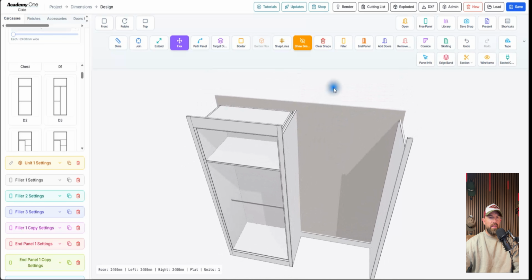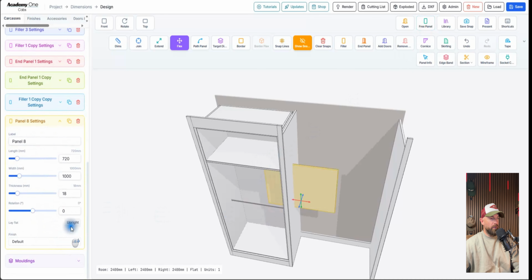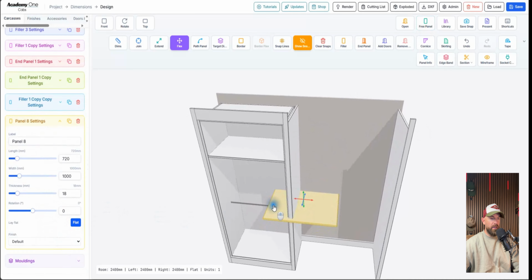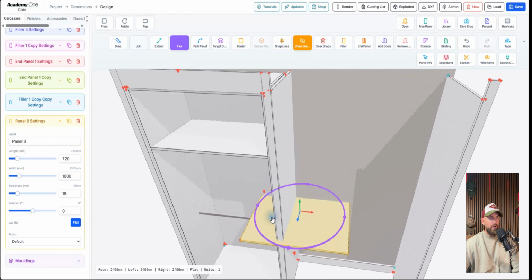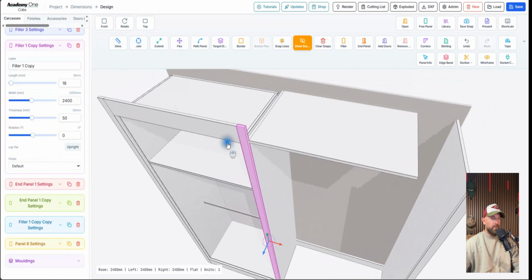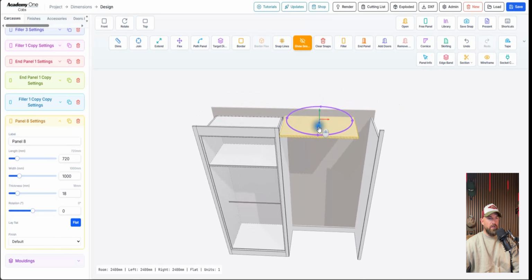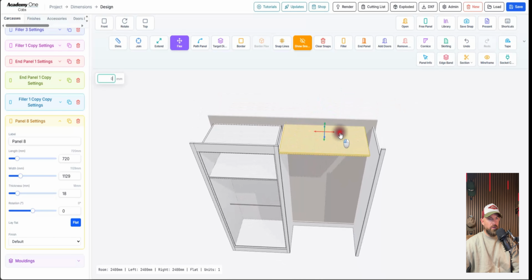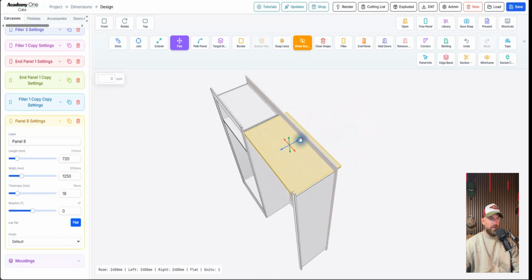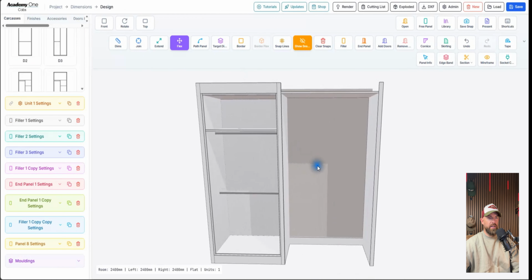And then the next thing I'm going to do is add a free panel in. I'm going to lay it down flat, and then I'm going to pop it up here. The way that I'm going to put it up there is I'm going to use join by corner. Now if I press J, because I've set up J for join by corner, I'm going to snap that into there like so. And then I'm just going to get the flex tool, extend it over and bring it backwards as well. Okay, so that's the section there.